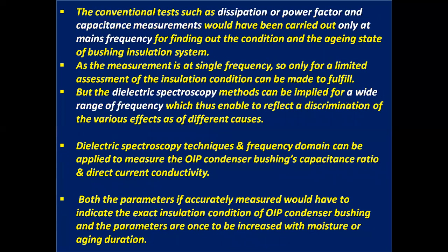The conventional tests such as dissipation or power factor and capacitance measurements would have been carried out only at mains frequency, that is 50 Hz, for finding out the condition and the aging state of the bushing insulation system.